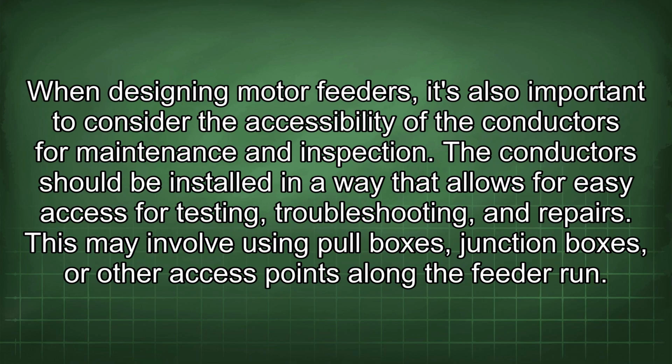When designing motor feeders, it's also important to consider the accessibility of the conductors for maintenance and inspection. The conductors should be installed in a way that allows for easy access for testing, troubleshooting, and repairs. This may involve using pull boxes, junction boxes, or other access points along the feeder run.